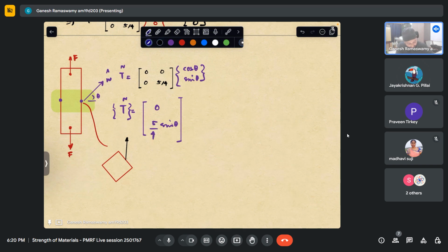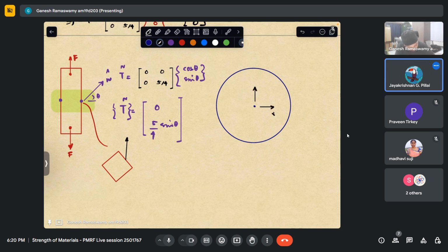So if I have a circular domain, in order for me to specify, in general, we take the r theta coordinate system. If this is xy, at any point, my normal to the surface will be radially outward. On this surface, what is the kind of load that I'm applying? The traction that I'm applying is what I will specify, which is why a surface will be characterized by its outward normal. And if it is a free surface, then naturally it will be stress free.